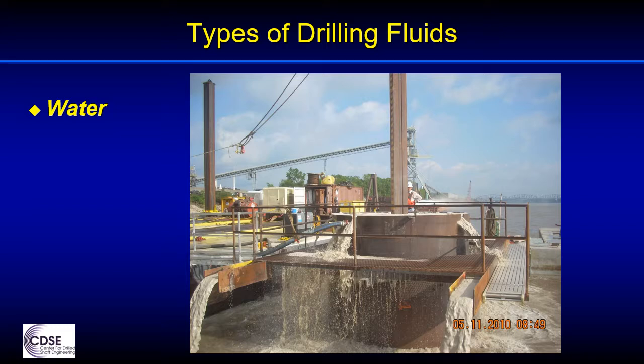Water alone can function as a drilling fluid in situations where the formation is inherently stable but permeable, such as some rock formations as noted earlier. Casing may be employed through unstable overburden to provide a stable environment to excavate the rock using only water.